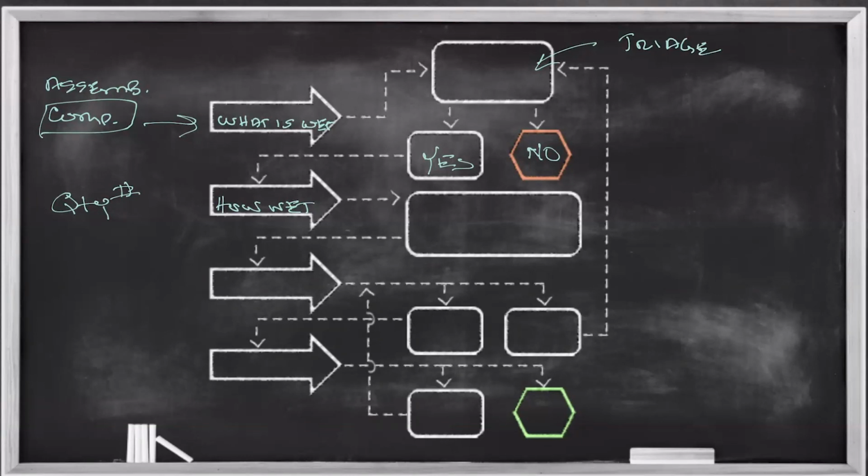Well, that puddle was extracted. The puddle isn't what's wet. What's wet is the absorption that occurred into the materials that were beneath that puddle, right? And if I don't establish a number on day one, whatever that number is, then when I come back the next day, I don't know what the next day's number means to me, right?